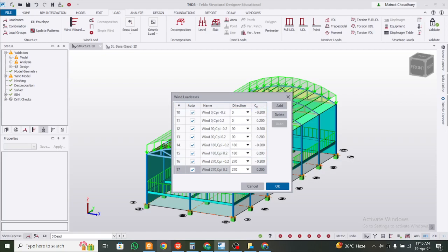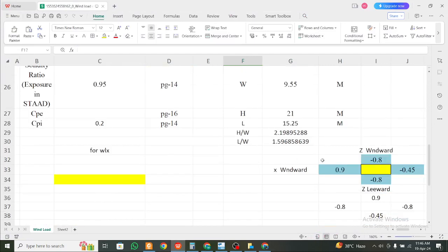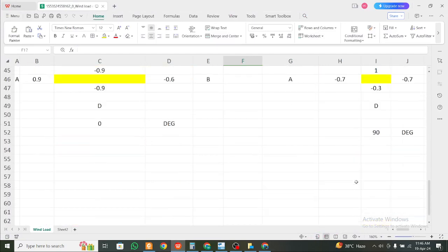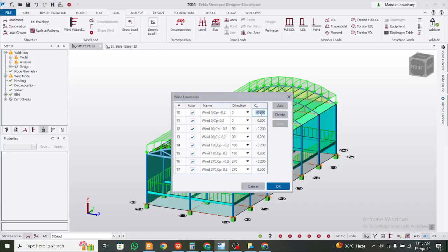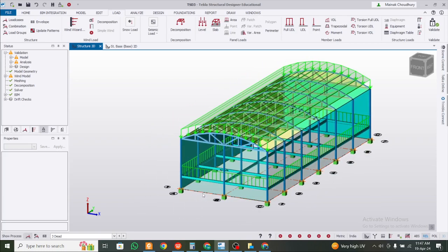but if you just check this particular reference in the windward side and leeward side, everything we can calculate, and then we can apply this. But I'll go a little bit on the safer side, and we'll go with 1 because generally it is never more than 1, so we keep the directions same, and we'll just apply 1 here. So we'll be on the safer side, and we'll also save some of the calculation time which is required, because that really takes some amount of time.